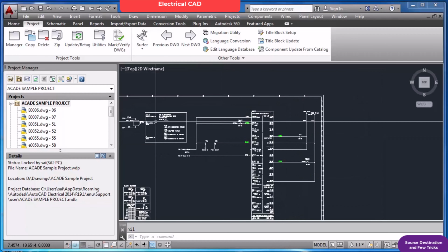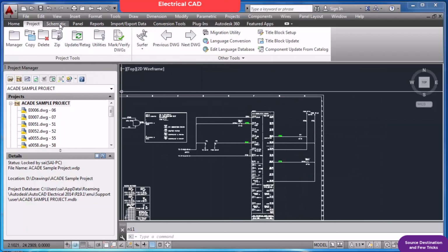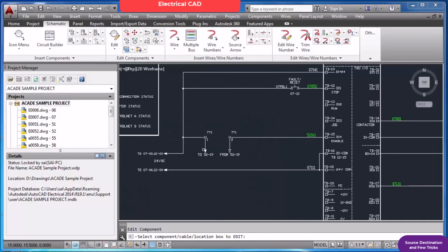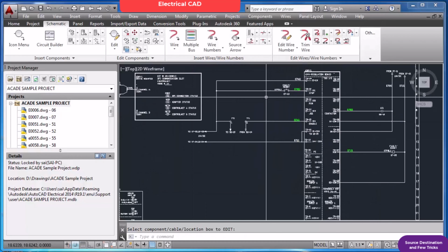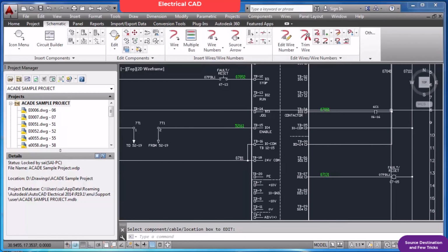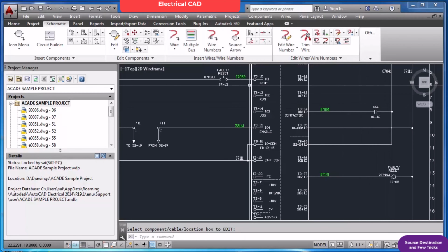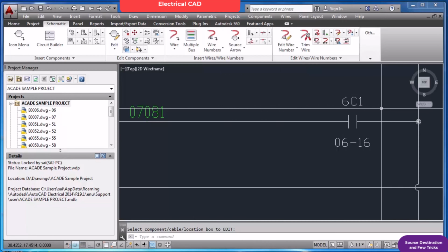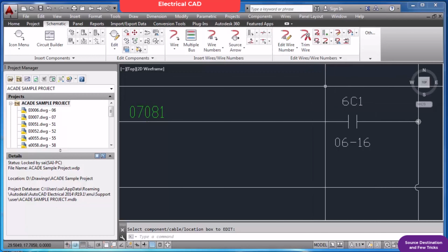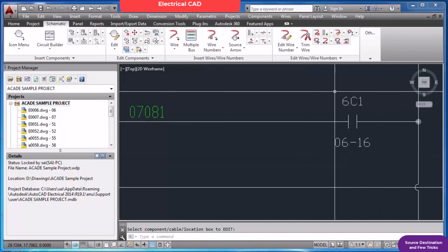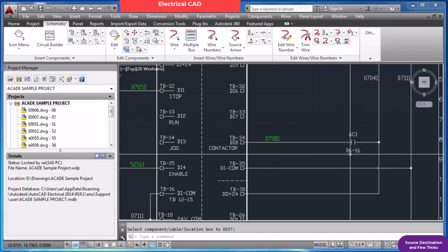in a single go. Even these tags inside this 7 will become automatically we can convert it into 22. Everything within this will update. Even this 6 will become 21. In sheet number 7 it was 6, but through writing some programs, when we save this into sheet number 22, this will automatically become 21. So you can customize the commands as well.